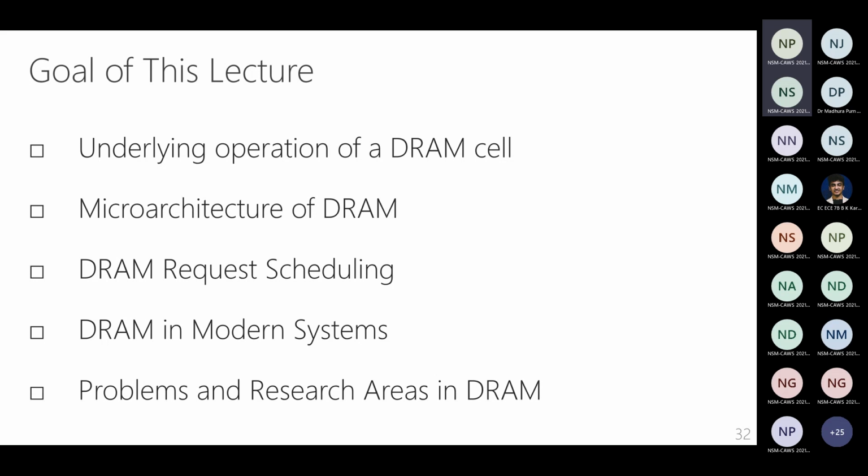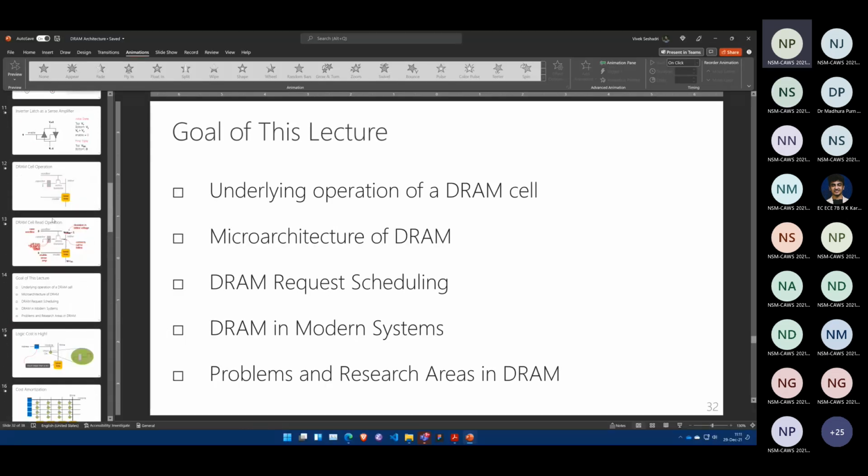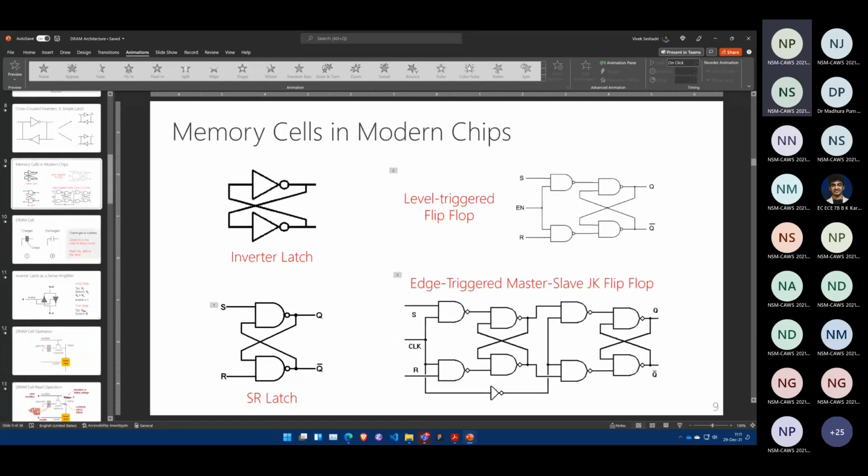How are SRAMs better than using register banks for caches? Let me go back to the slide. So this is your SRAM, the basic cell in your SRAM. Each inverter is 2 transistors, so you have 4 transistors here. This is your register. Imagine how many transistors there are. Each one is a NAND gate, and a NAND gate is 4 transistors. So you have 4 times 8, at least 32 transistors in this logic. And there's also an inverter here, which I'm not including.